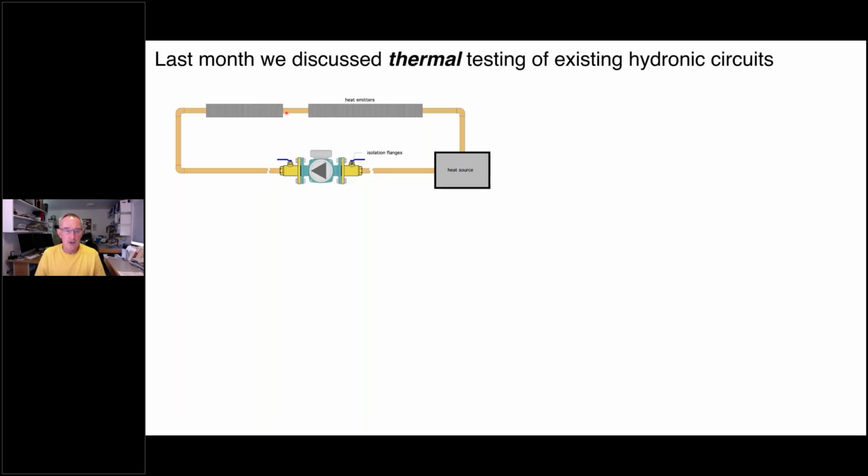And these are questions that would come up not only in the context of adding a heat pump to this system, be it air to water, water to water, geothermal, but in general, if you're adding a heat source. A good example would be, let's say we're replacing a cast iron boiler with a wall hung boiler. That wall hung boiler is going to have a very different drag characteristic or head loss characteristic.